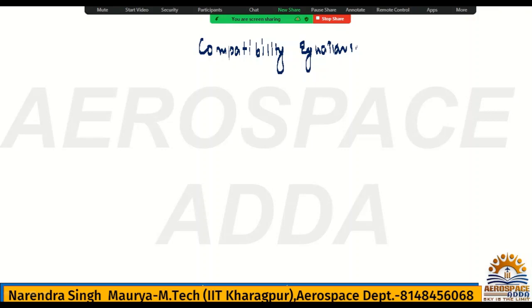Okay, so these are basically the relationship between the strain and displacement. Already we had seen the relationship between strain and displacement. Six strains are defined in terms of three displacement functions. Already we had seen u, v, w were the displacements, and the six strains were epsilon x, epsilon y, epsilon z, gamma xy, gamma yz, and gamma zx. That we had seen. Okay.